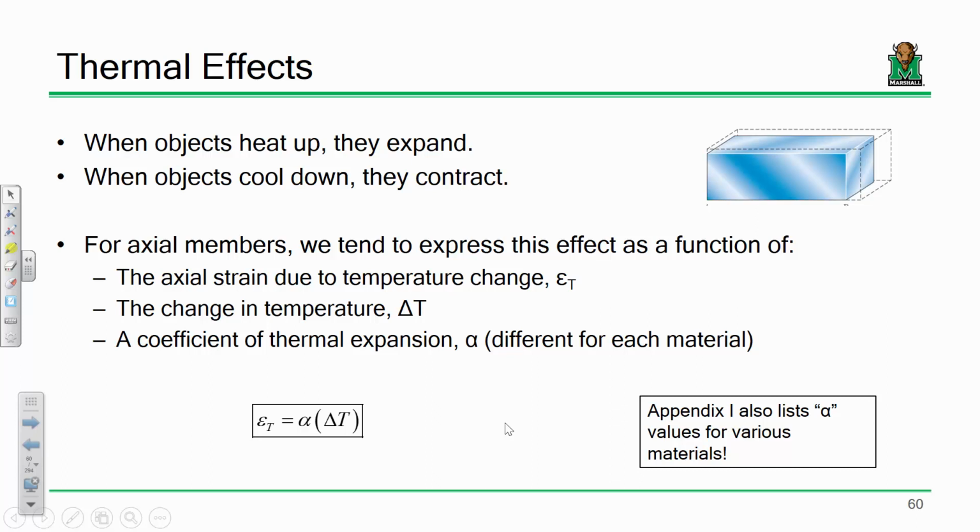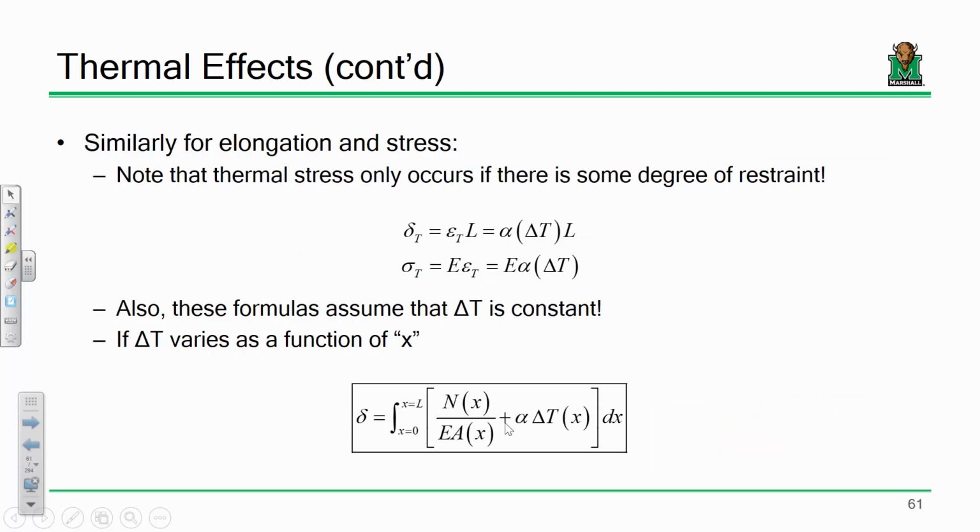Well, if you took that concrete element that's reinforced and you really heated it up or really cooled it down, you wouldn't want the concrete and the rebar to be expanding at different rates because then it would debond and it would want to crack. So it's sort of a nifty little thing about concrete and steel that their alpha values are very, very similar. So they're not the same, but they're pretty close. So that really doesn't happen very much. So just a little factoid about civil engineering.